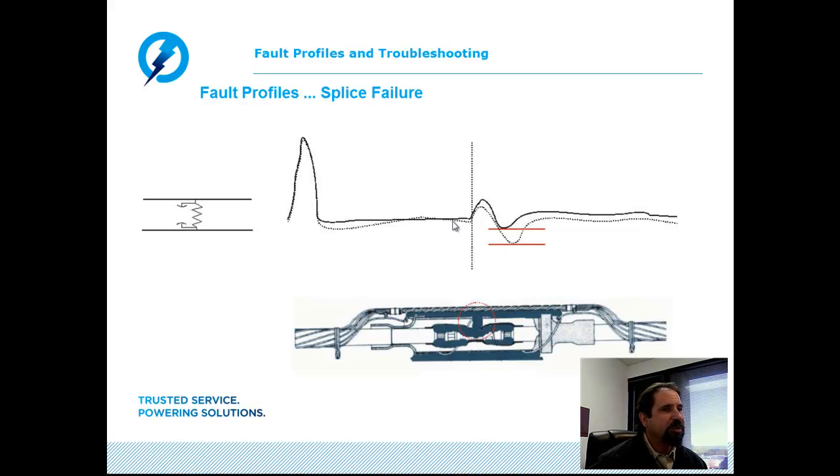Now, the radar pattern will definitely help us with the next clue. Do I physically see the traditional pattern for a splice? I see that there's a pattern for a splice. I'm getting a very high voltage breakdown. It may not be breaking down on every thumping cycle. That immediately alerts me that I need to examine and study this splice pattern.